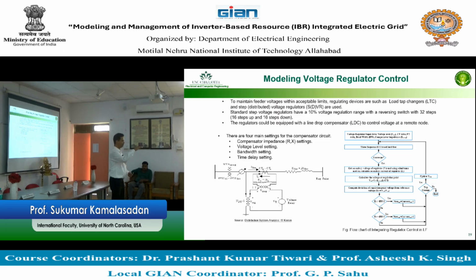So what happens if you do multiple power flows without taking a regulator? At one point, power flow is done. Next point, power flow is done, taking care of the voltage. But the regulator is changing the voltage. Do you need to consider that or not? Ideally, yes. Otherwise, your power flow solution is not correct.